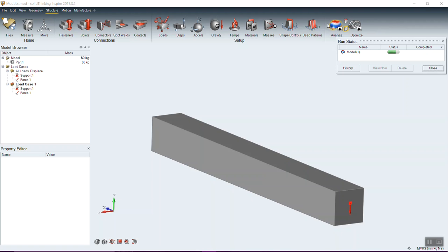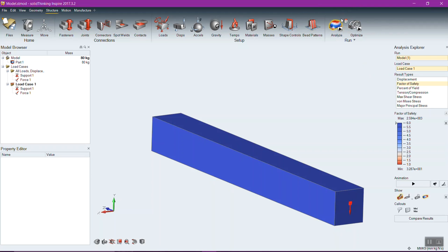And now, if you've never run an FEA before, you can officially say you've run an FEA. And in a matter of minutes or seconds here, it should be done. We'll get a little green flag above our Analyze. We can click the little green flag, and it'll automatically take us into the post-processing mode. If we click the play button,